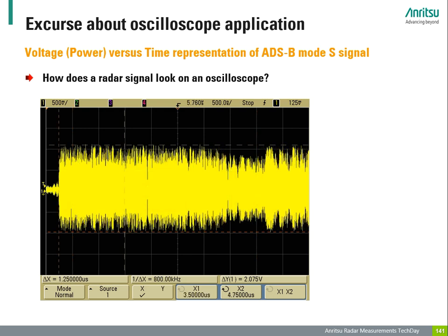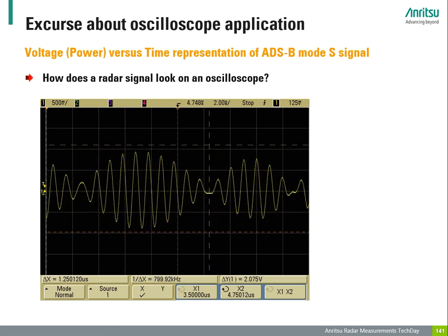Remember, I mentioned that it might be of interest to check if a phase change really happens at the given point in time in the signal. This point that we are looking for is visualized by the second dotted line from the left. Another zoom is clearly showing the expected behavior as we are seeing here. Be aware that you can also calculate the peak power of the signal based on the measurement. We have here voltage over time at the 50 ohm impedance.